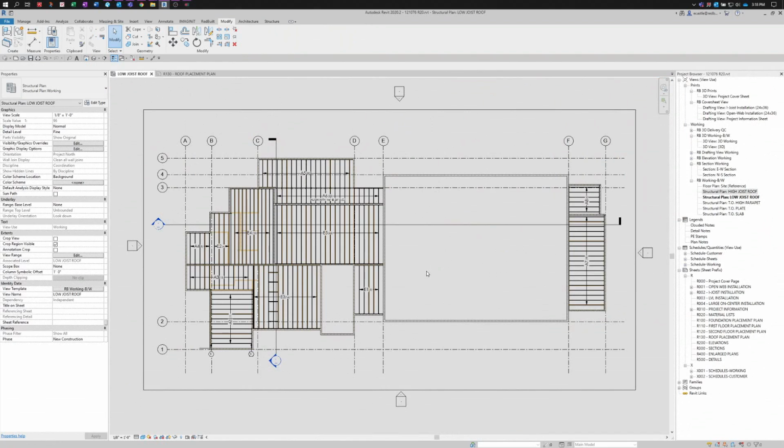Now that I've completed my review of the 3D model, I'm ready to set up my views for my sheets. We want to do this prior to adding any kind of annotation, symbols or dimensions or text, because if the view will not fit on the sheet, then I'll have to change the scale of my views.